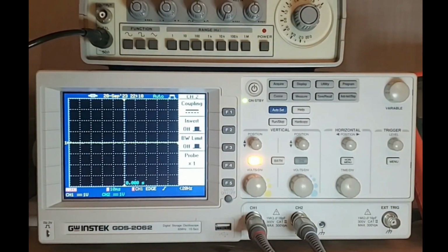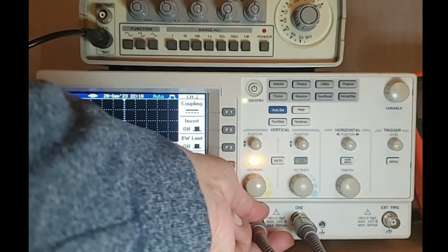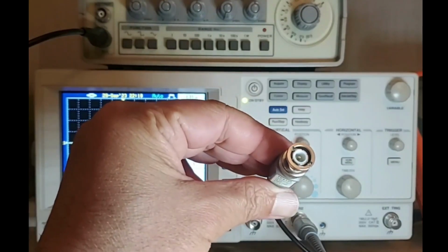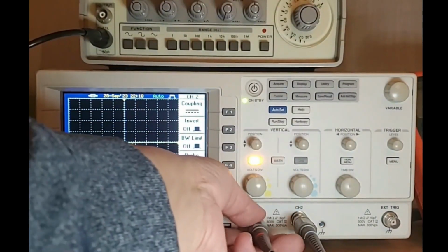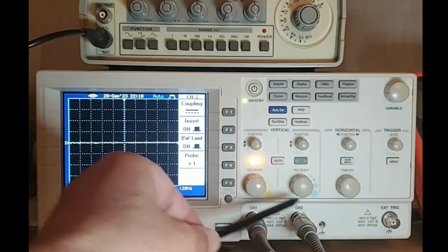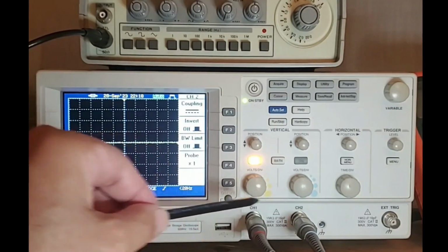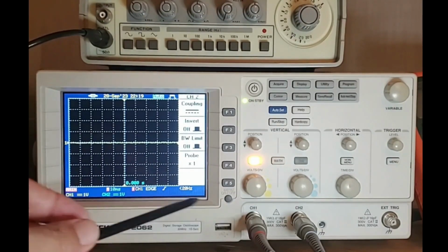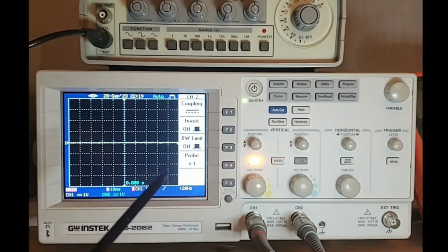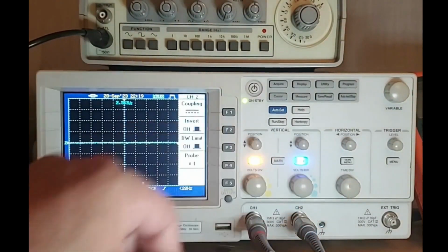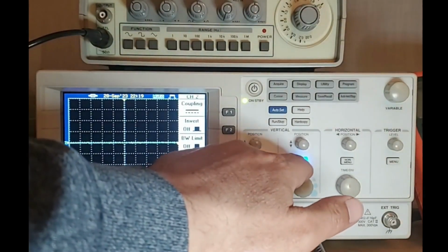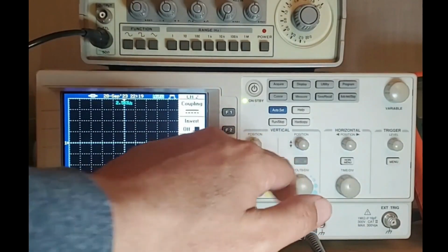The probe on the other side has a BNC connector, as you can see here. We can just connect it to one of the two channels of the oscilloscope. I have a two-channel oscilloscope, as you can see, channel 1 and channel 2. This means I can see two different voltage waveforms as a function of time simultaneously. Right now, I have turned on only channel 1. If I want to see both channels, I can turn on channel 2 as well, and then I will be able to see both waveforms at the same time. For now, I'm only interested in channel 1, so I will turn off channel 2.